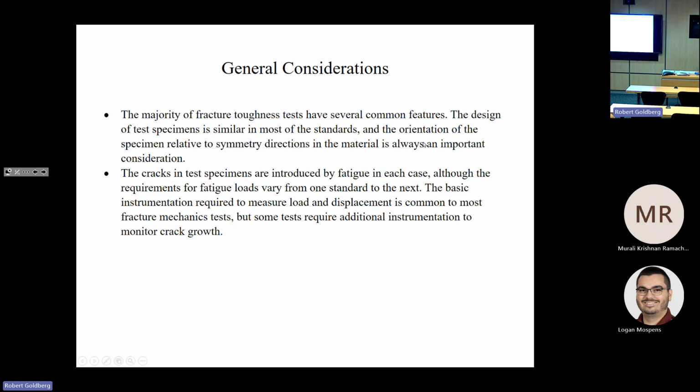But in reality, due to the ways that metals are rolled or extruded or forged, a lot of times there's at least a little directionality in the response of metals. So the standards take that into account. And that's even something in terms of modeling and analysis. Sometimes if you find your analysis isn't what you expect, depending on the material you're looking at, it could be that there's orientation dependence on properties and responses that aren't accounted for in your analysis.